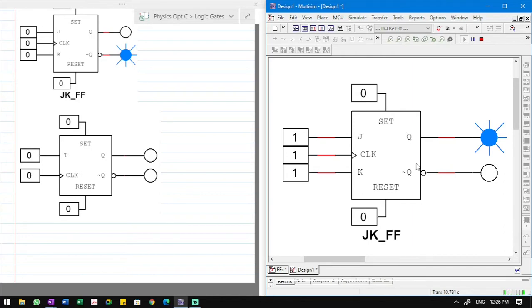Now the JK flip-flop itself could be used to construct any other flip-flop, right? So the JK flip-flop is basically a universal flip-flop. So the clock controls the output. In particular, the clock toggles the output terminals. Both of them toggle, and they're always opposite each other, of course, when the clock goes from low to high. When the clock goes from high to low, nothing happens, and I am demonstrating that. So only when the clock goes from logic 0 to logic 1 do you have the outputs switching, right?